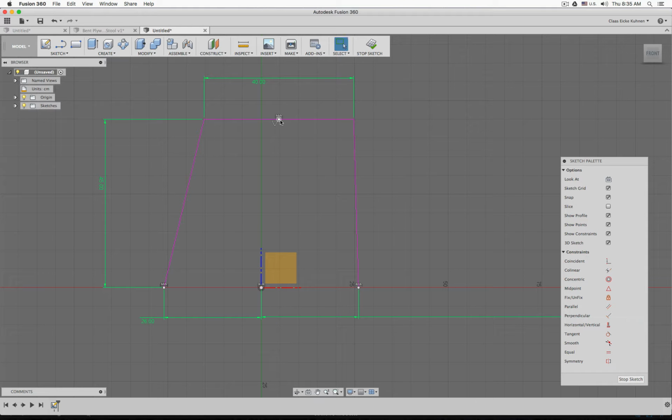And then I try to move this one a little bit closer, so it's vertical over the world center, and then I say vertical constraint to there. And now, because the point is vertically constrained to the center, and the point is constrained to the midpoint of the line, the line will follow wherever the point is. Okay, so this is good so far.